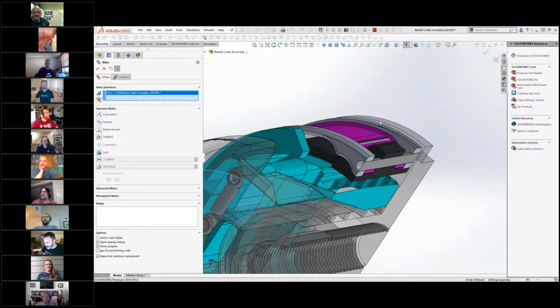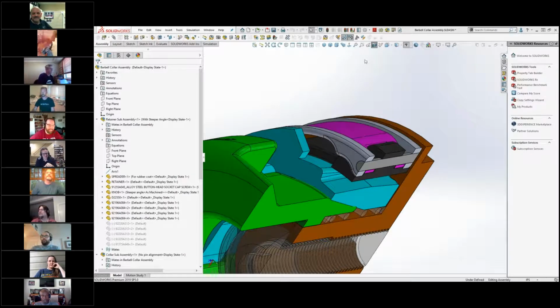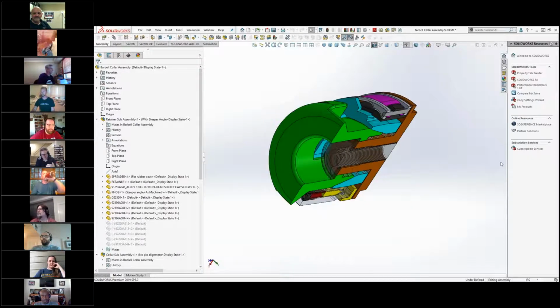Oh, kind of the same vein. What is something you rediscovered about SolidWorks that you wish you'd never forgotten? We just touched on that, because the Alt to hide and the Shift Alt to bring it back was something that I remember when it came out, and then I never used it. And I was at a rollout and they were just doing something and they showed it. And I was like, ah, crap. I use it all the time.